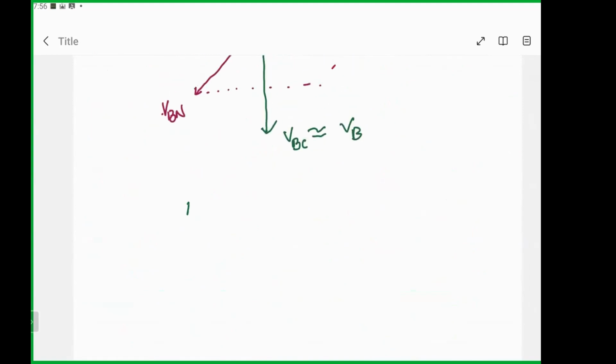So this is simple Ohm's law. So IAN is equal to 239.6, making an angle of 0 degree, divided by resistance, whose phasor angle is always with the reference. That means resistance is always in the horizontal line, XL or XC is the vertical line, and impedance is in between.